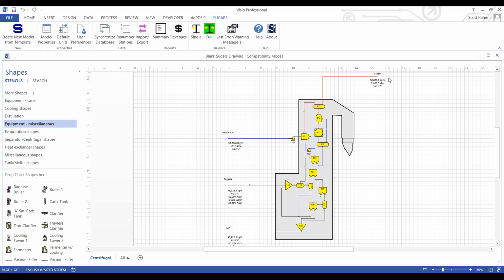It all ends up in the steam as it comes out at the specified pressure, which we specified in the feed water pump, and temperature, which we specified in this blender station 114 here near the end. So that all looks good.